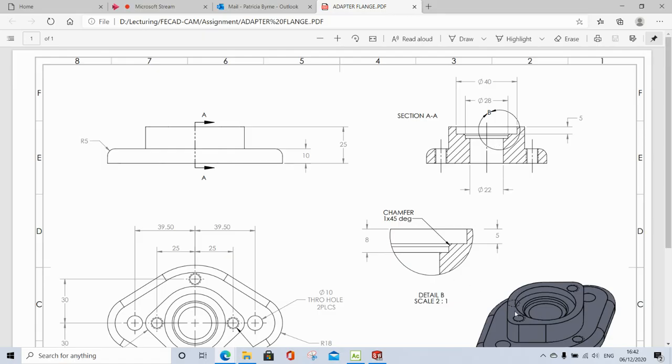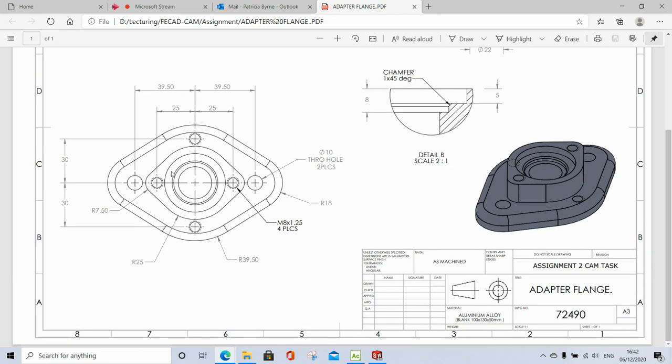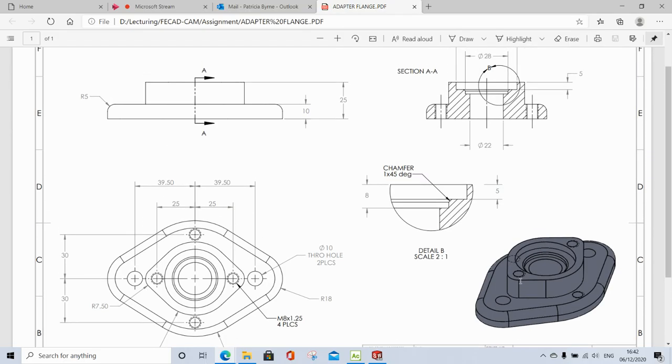Okay, so I would advise probably to do these holes first and then get those tapped, and then go and start doing the pocket and do the chamfer at the very end. So remember to look at the videos. There's 2 ways of chamfering. You can do it by offsetting the line. So it's a 1 millimeter chamfer at 45 degrees. So you can offset the line in by 1 millimeter, or you can lock the tool paths above. The only thing is you need to be sure that everything to that point is right, because once you do that, it's very hard to undo.